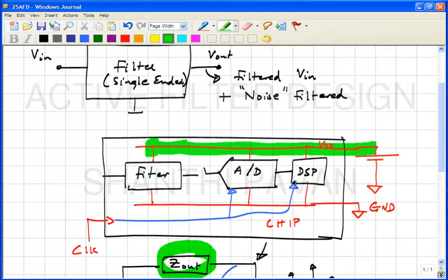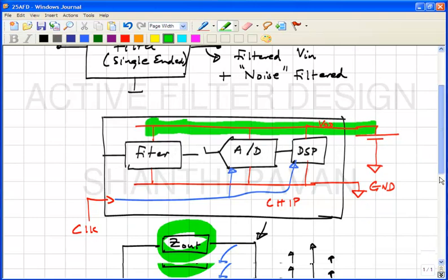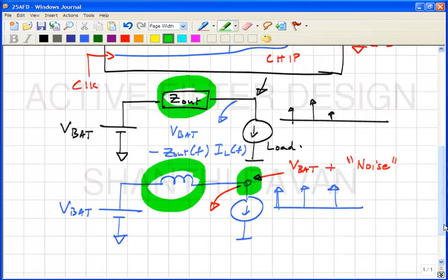What do you think you can do to fix this to some degree? What is the problem? The problem is that the battery has got an inductive output impedance, right, which means that if you attempt to draw spikes of current from the battery, you will see a big dip in the voltage.